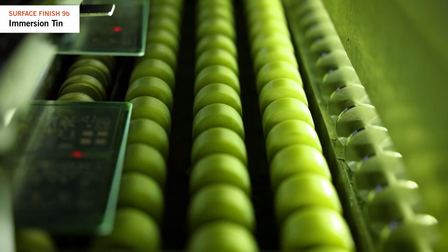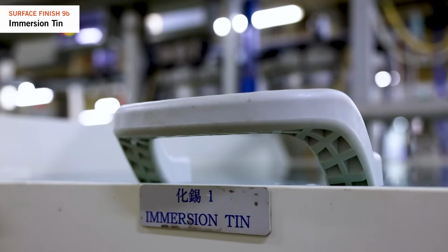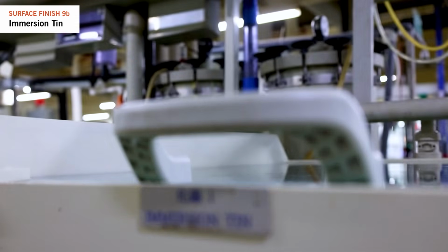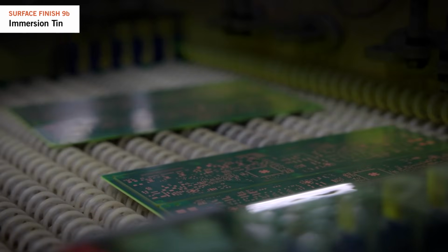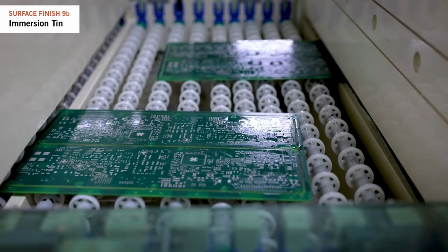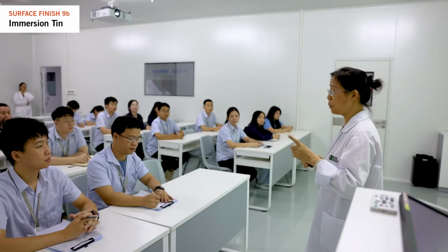Next, a pre-cleaner with acid removes contaminants, followed by rinsing. A stronger acid micro-etch roughens the copper surface. Tin is then applied, forming a thin, flat layer on the surface, forming a bond with the copper layer. After that, the PCB needs cleaning in warm water, followed by thorough drying to prevent staining. This process ensures a shiny surface when dried.